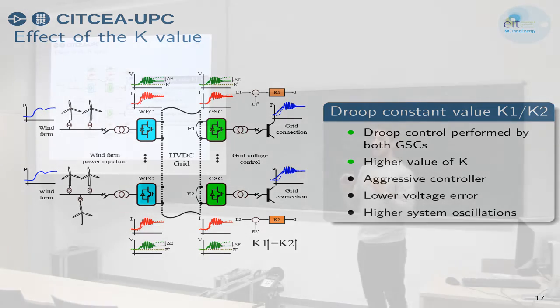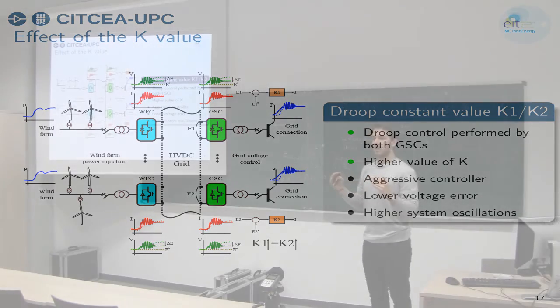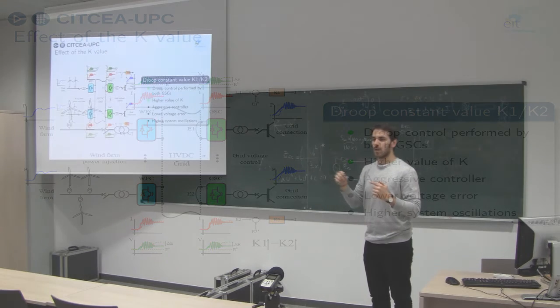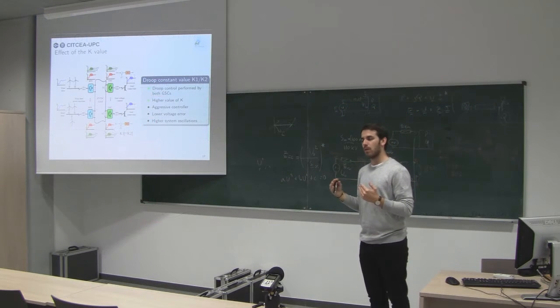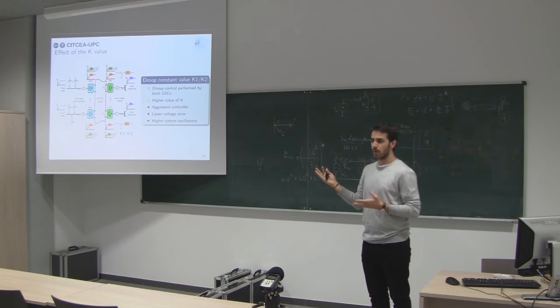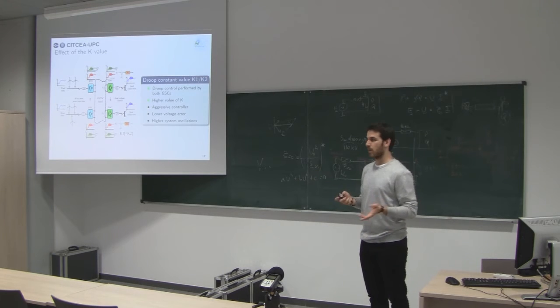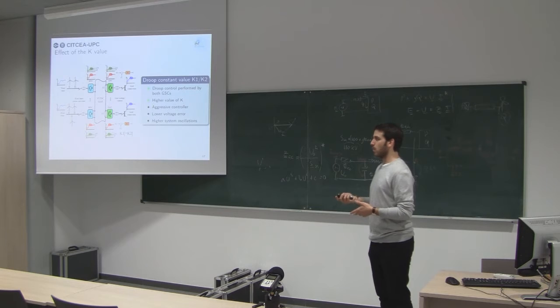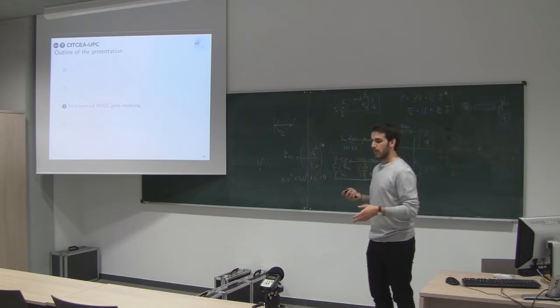And we don't want to trip the converters during operation. We don't want to exceed 1 per unit in current, or 1.1 per unit on the converters, right? Because otherwise we will burn them, or we will trip them as soon as they see a large current flowing through them, right?